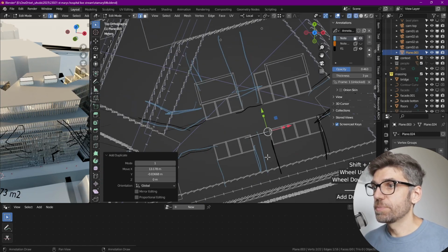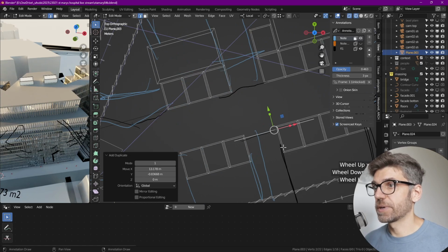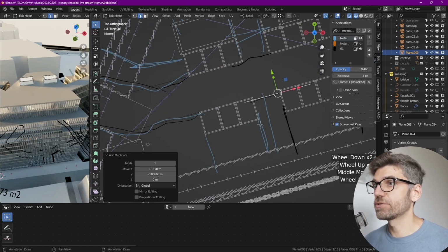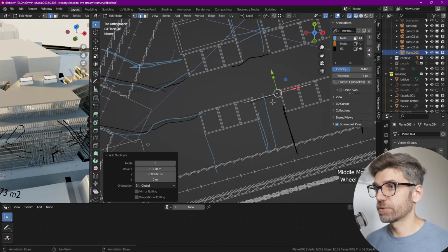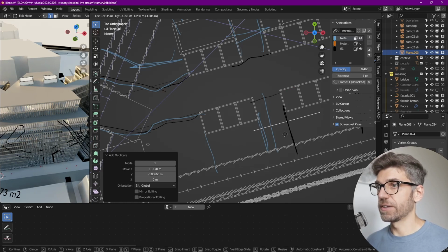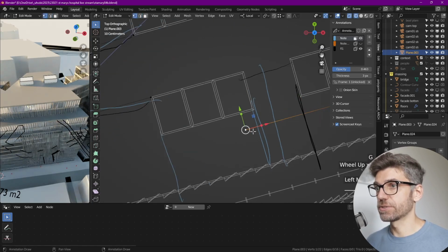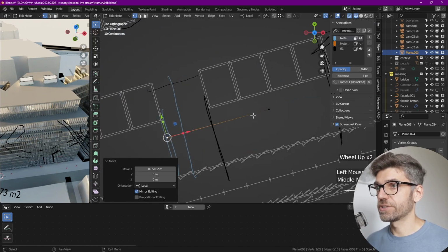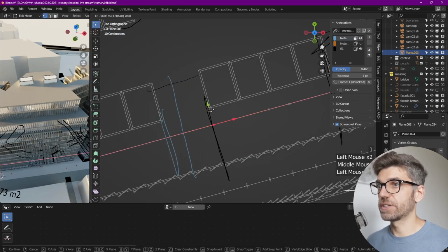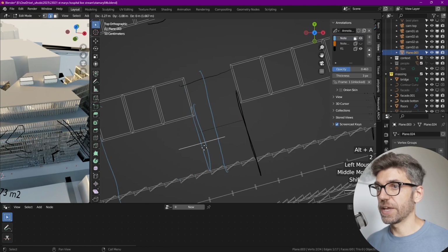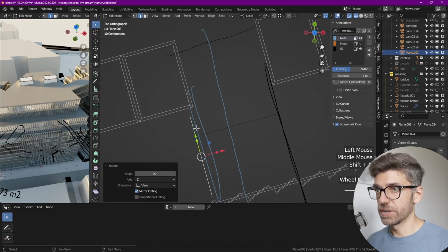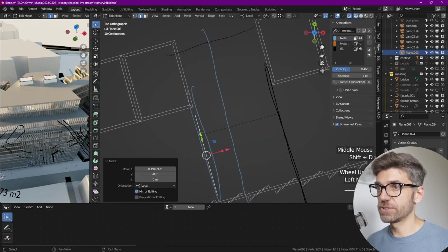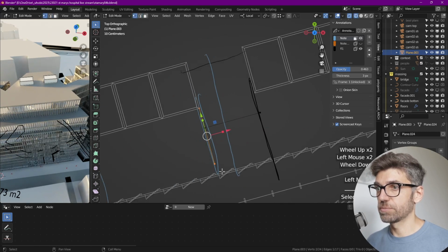This here could be a suite. So we can have some kind of doors situation in there, so you can enter either on one side or on the other side. And we can do something like that in here. So we've got an edge that's aligned to here, an edge that's aligned to there. Let's duplicate this, rotate it 90 degrees, snap it along that edge, and then like that, and move that.